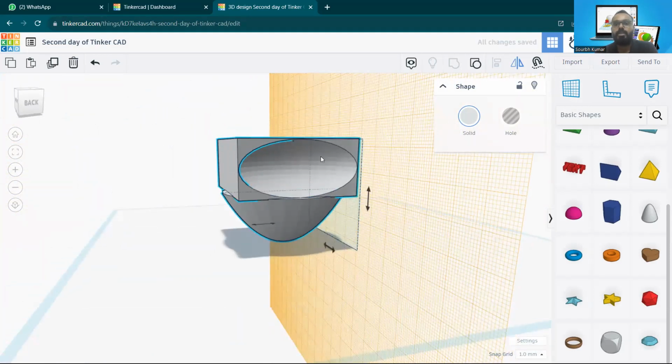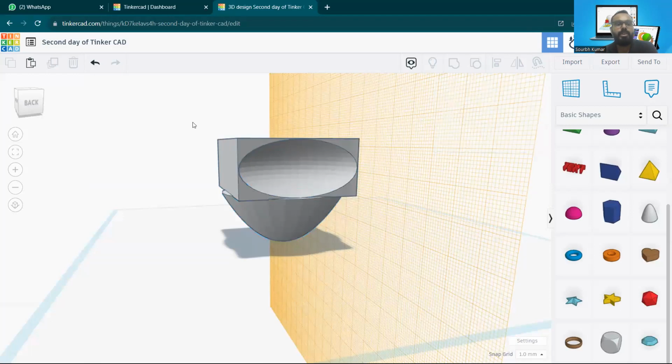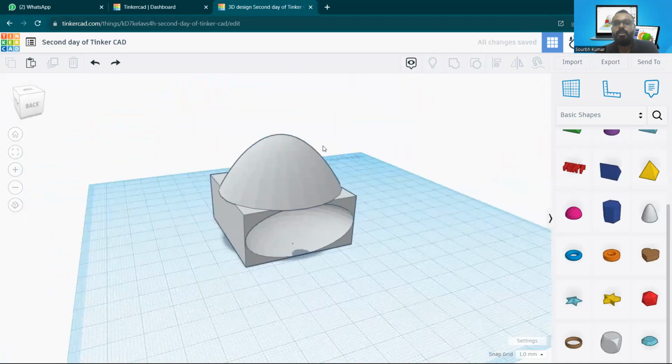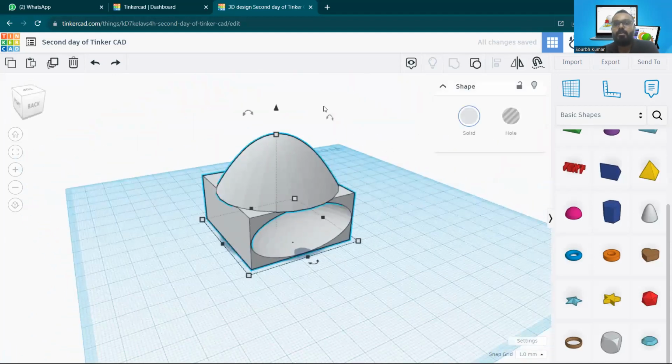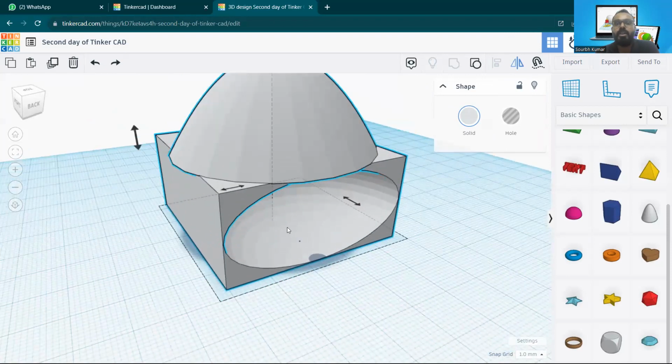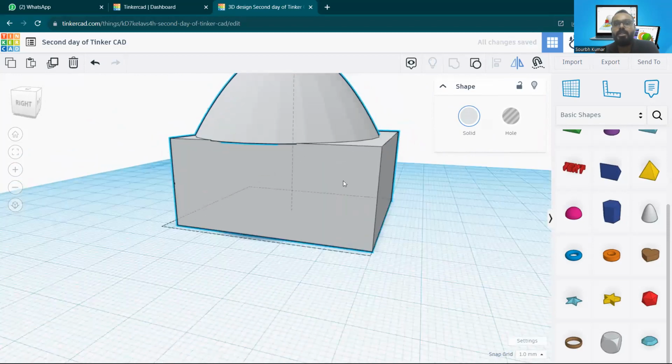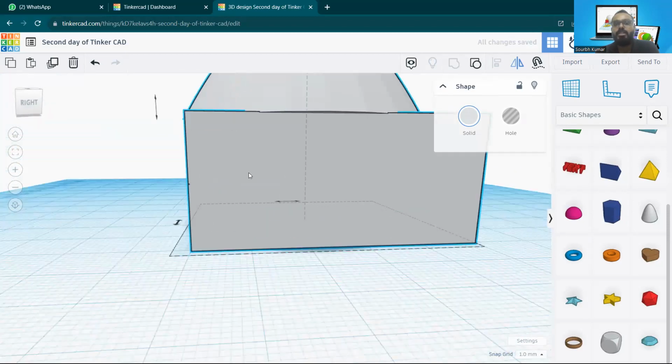Basically, what is happening here is we are mirroring it. Control Z. Okay, fine. It won't reflect here because our object is identical on each of the sides, but here we do have a non-identical side. We have one groove cut in front of the object, right? So if we click on these arrows, it will reverse. It will mirror the object on the other side.